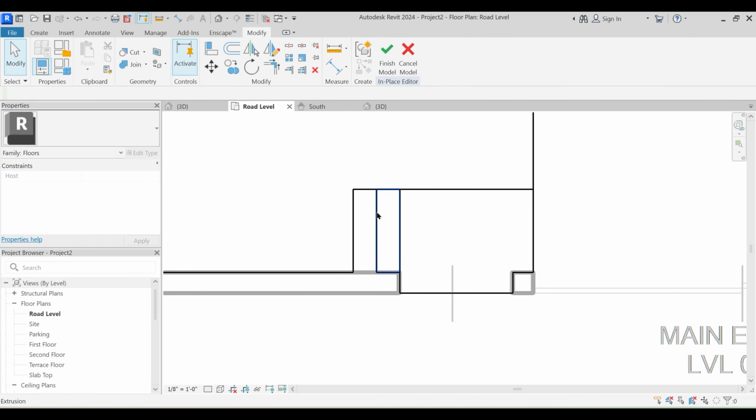And what is the max ramp slope? That is the unit distance you travel in length divided by the unit distance you want to travel in height, that is in y direction. So that divided by the plinth is 2 feet. So this divided by 2 feet. So you just need to sit with the calculator, and I have just already done it. And maximum ramp slope, this particular variable, is 5.5. Okay. So with that, I'll just say apply and OK. And yes, one more thing, this should not be thick, but it should be solid.